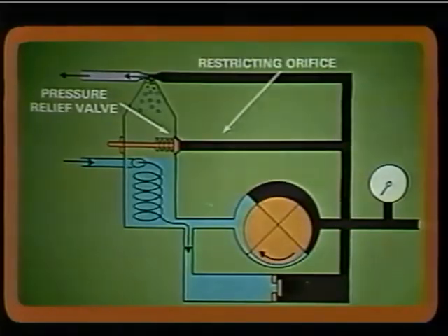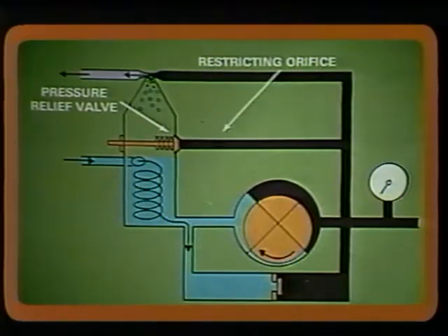To overcome this difficulty in the Teledyne Continental system, a relief valve is installed in series with the orifice. And during low RPM, this relief valve holds a calibrated force against the bypass fuel, producing accurately controlled pressure in the system for idling.